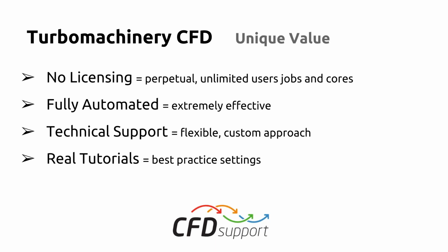And the last one would be the real tutorials are included. So TCFD users have no doubts about the best practice settings. There are included real machines that are already preset. So you can basically take one of those tutorials or preset machines, replace the geometry with your own, modify the settings, the boundary conditions, for example, and just run the simulation. So it's prepared, it's ready to use.